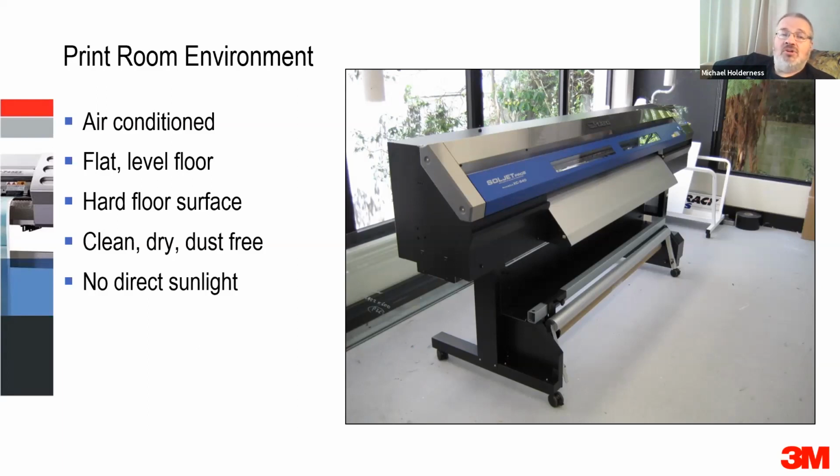Anytime you get that under your printer, you're going to get it kicked up and it will contaminate the print surface from time to time. Not immediately, but commonly it will contaminate that surface. So you do not want carpet. Clean, dry, dust-free is what you're after. So you want a floor that can be cleaned and dusted and vacuumed and even mopped.